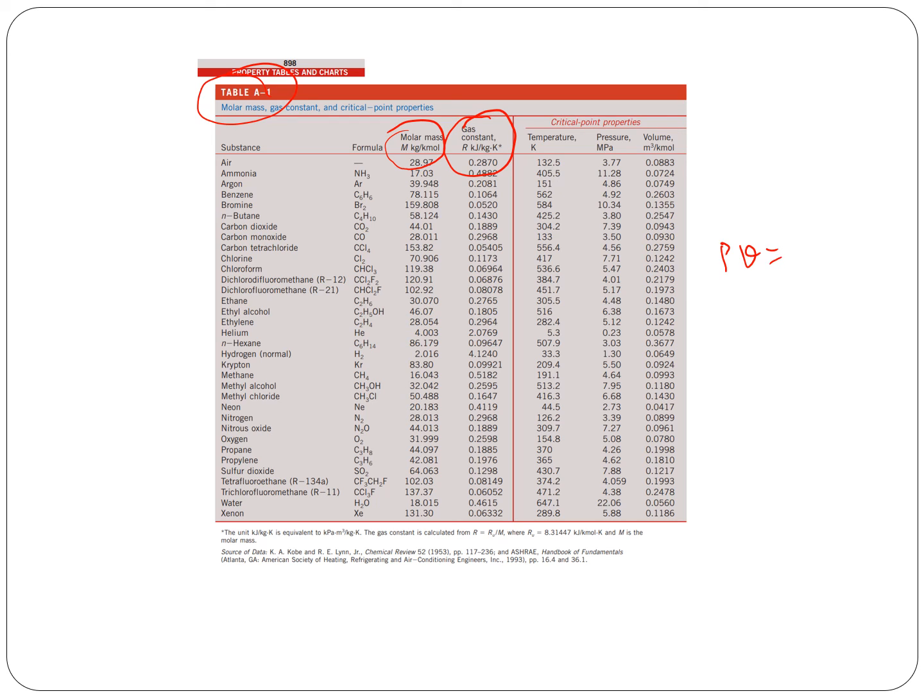Pv is RT. So the gas constant, depending on what gas you are using, you need to look at. If it is air, R is this, and remember the unit is in kilojoule per kg per Kelvin, so you need to be careful in changing the unit so that you get the basic answer unit system.